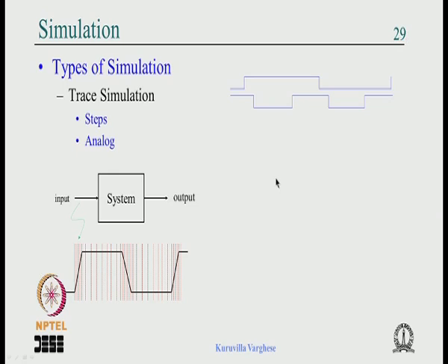You can imagine this is a digital system now, and we are giving some input to the system. Now you see this input is changing like that, and this one is changing like this. Suppose initially, at the first step, the simulator takes these values 0 and 1 and computes the output. The moment it is computed, there is no point in dividing this into minute intervals and computing it, because it is going to be stable, because the digital system is binary.